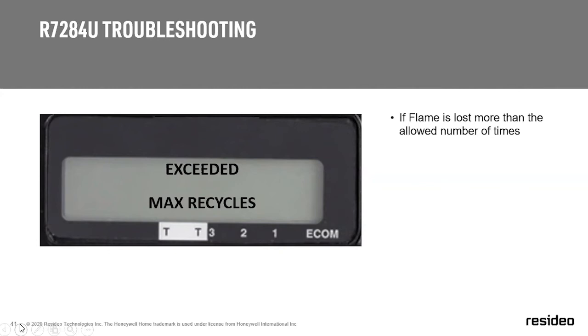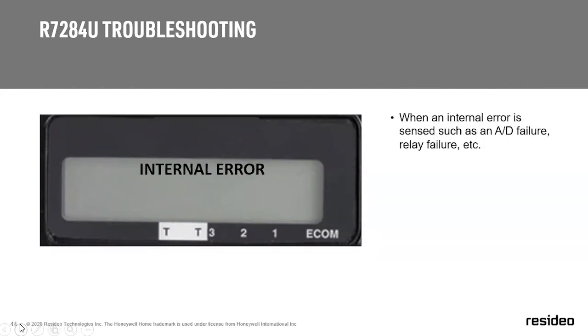So I tell guys, look for dirty oil filters, a suction leak or something. That kind of explains what the control is trying to tell you when you see that exceeded recycles. Thanks, Rick. Good pickup. Yeah.